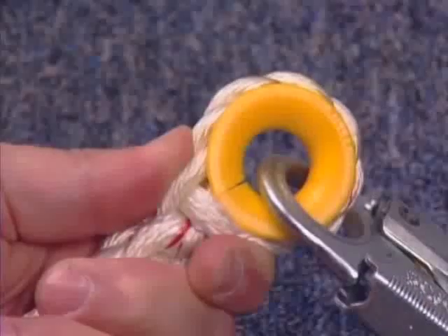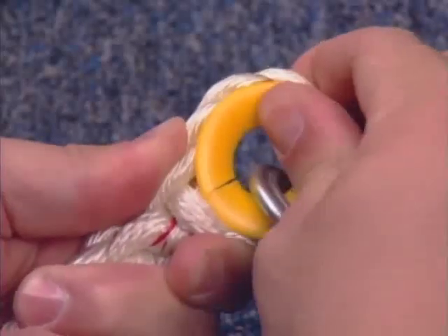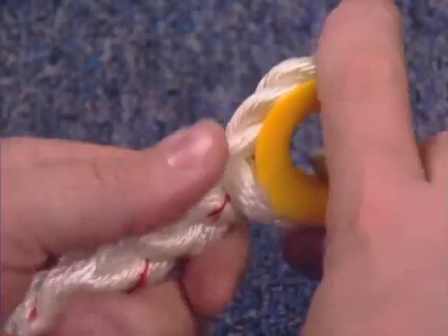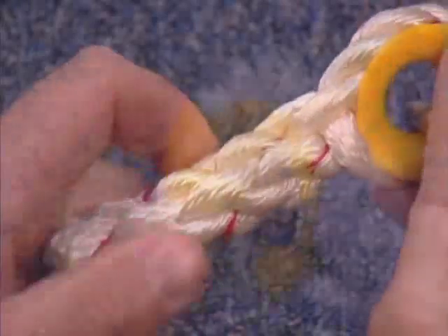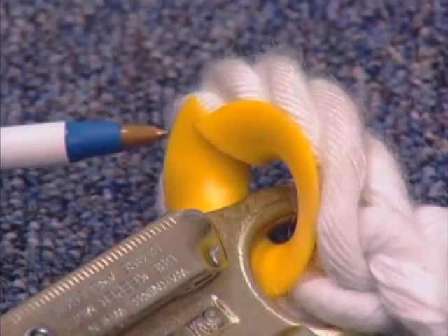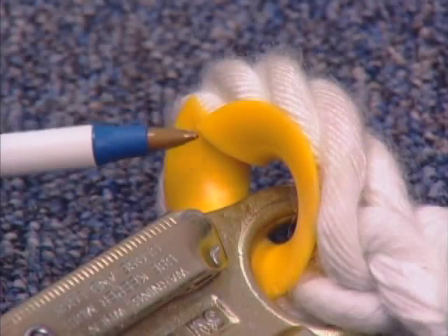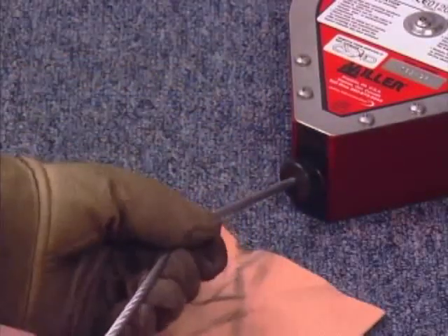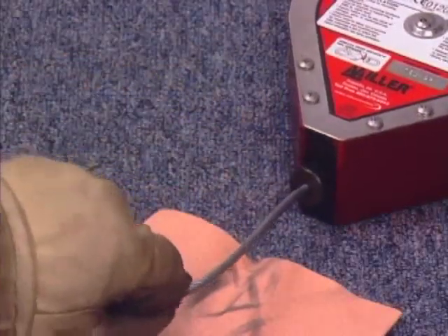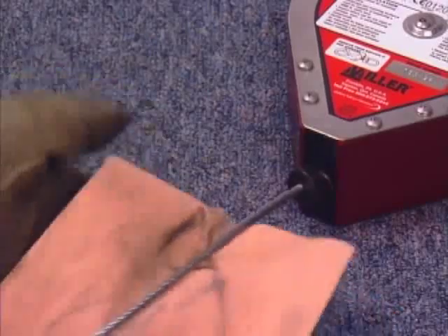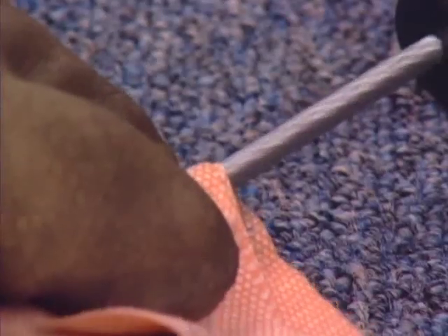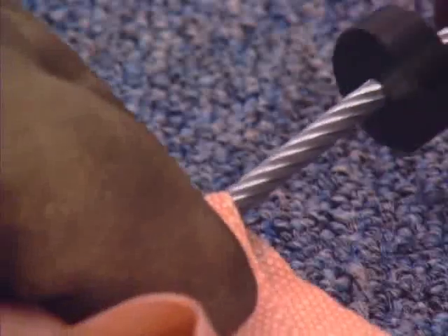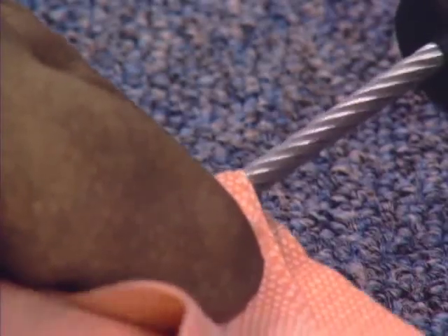The thimble of a rope lanyard must be firmly seated in the eye of the splice and should have no loose or cut strands. Look for distorted or doubled over thimbles in the eye of the splice. Steel cable on a lanyard or retractable should be rotated while inspected for worn or broken strands. Wear gloves and use a cloth to run over the length of the cable to check for broken strands.